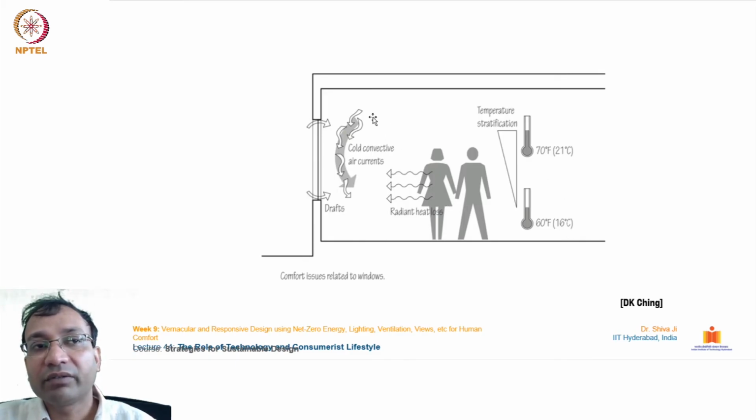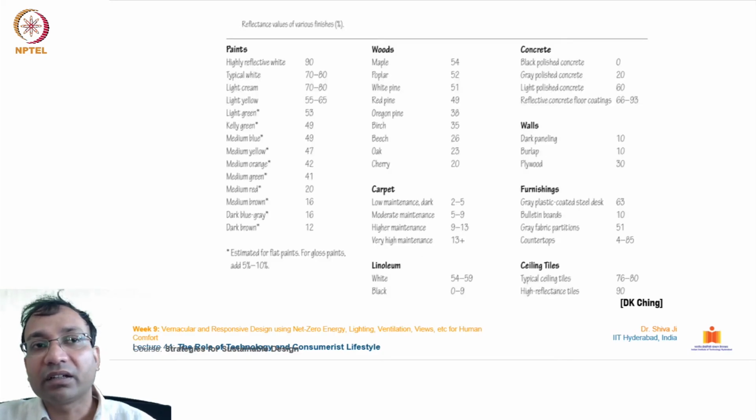So the cold convective currents go down, as you may be aware, and the hot convective currents go to the top level. Then from the ventilators they go out. This is how natural ventilation, this convection system, works inside a confined space.